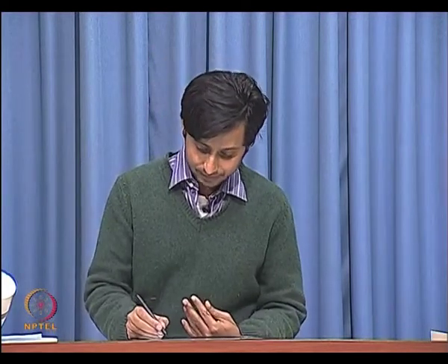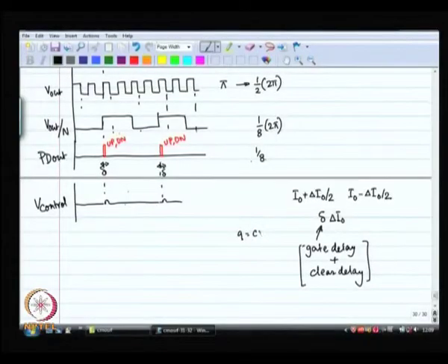All right. This charge, of course, is going to get accumulated onto that capacitor, which means Q equal to C V, remember. So, the voltage that you get, the extra voltage that you get, is this divided by the capacitance C plus C x. That is the extra voltage that you are getting. Fine. So, if this capacitor size is extremely large, then it should not matter, this delta voltage is close to 0. That is also true. Okay. Now,